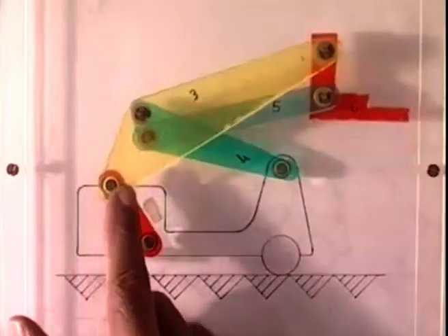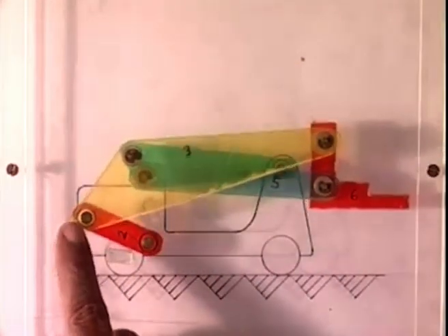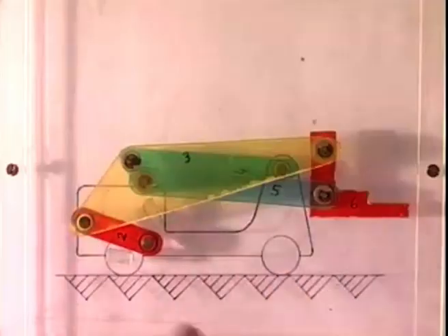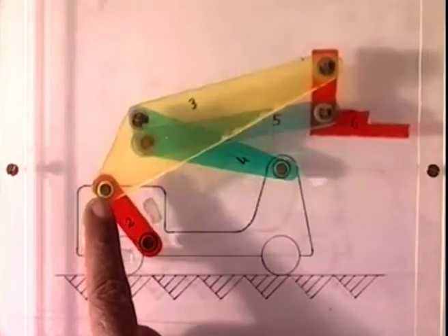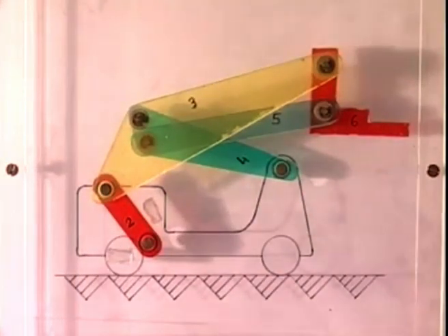So the techniques that we have learned for function generation, motion generation and path generation can be synthesized together to have a multi-stage synthesis problem for even more complicated problems. So in today's lecture, we have designed a 6-link forklifter using only revolute pairs by a multi-stage synthesis process, which are basically combination of the 3-position synthesis for function, motion and path generation of 4-link mechanisms, which we had discussed earlier.